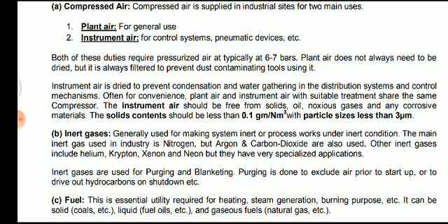Both of these duties require pressurized air, typically at 6 to 7 bar. Plant air does not always need to be dry, but is always filtered to prevent dust contaminating tools using it.